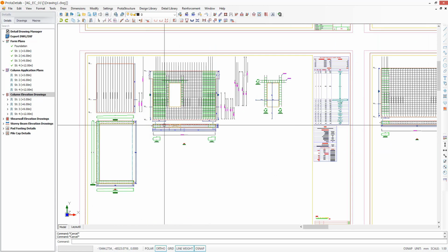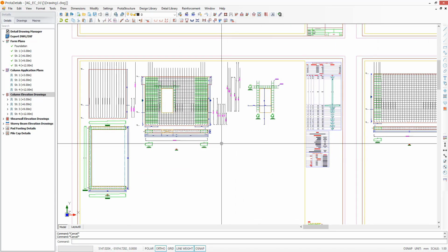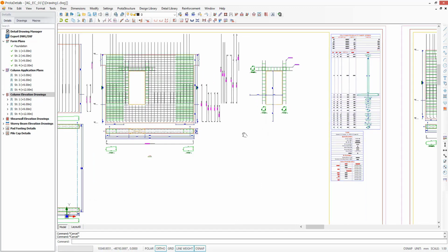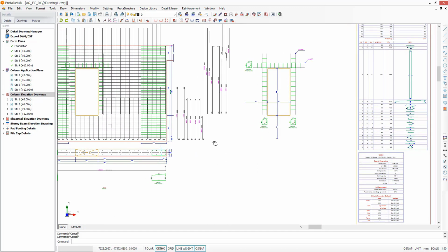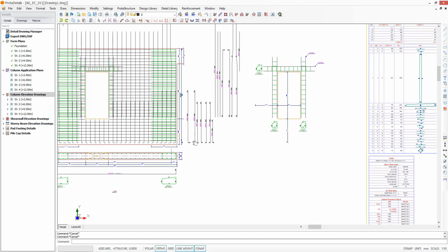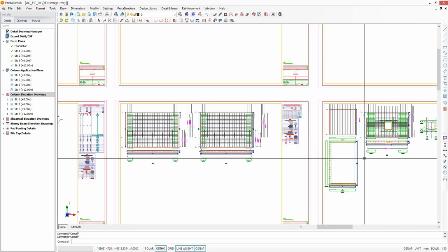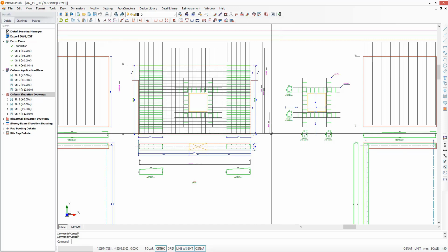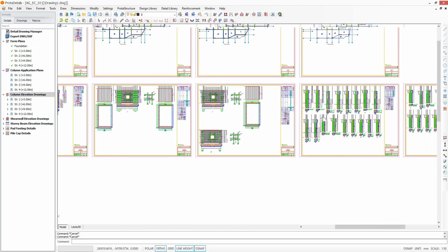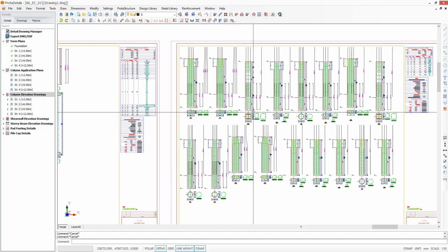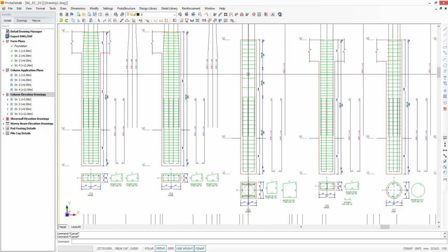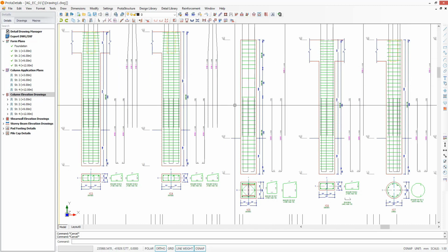Let's take a look at the shear wall details. Well, column, shear wall, and core wall details are generated with high precision. So for most cases, you won't need to edit them manually. And of course, this will save you a lot of time. And shear wall holes are displayed in elevations, detail sections, and schedules along with the required rebars. So you don't need to worry about the code-compliant hole detailing at all. Well, column elevations are laid out neatly as well. Well, the confinement regions are detailed according to the code provisions.